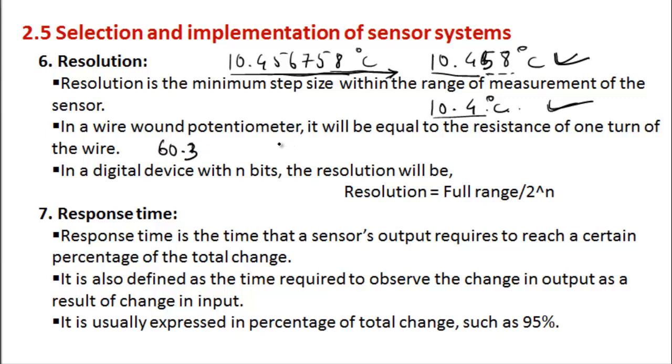Some will give your weight as 60.342. So what does it mean? It means that this is more accurate? No. The accuracy is almost the same. But here the resolution is more, because it is giving you more smaller values.